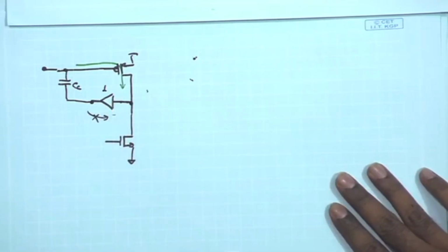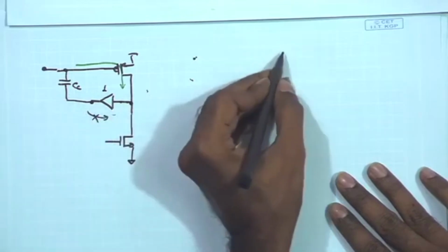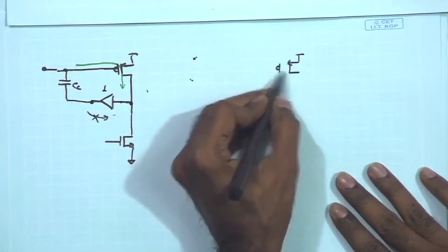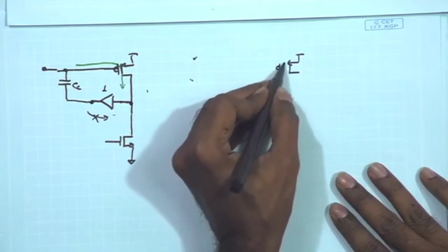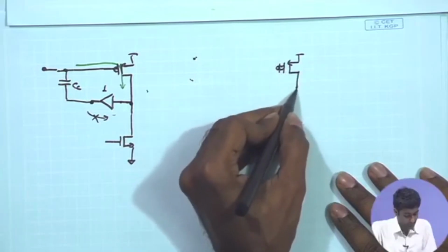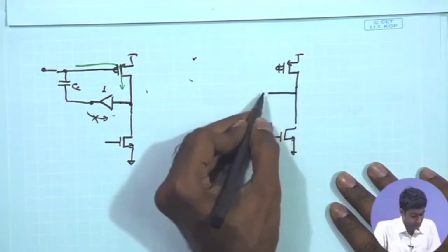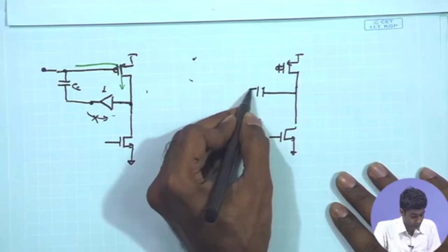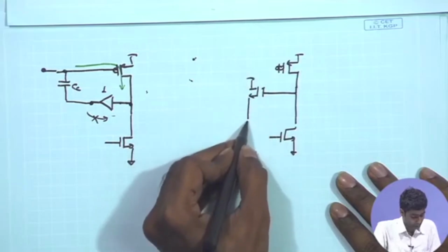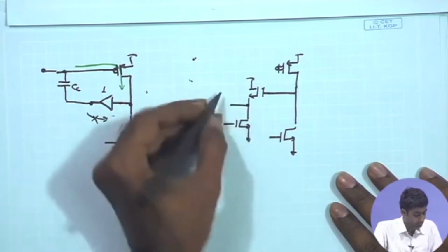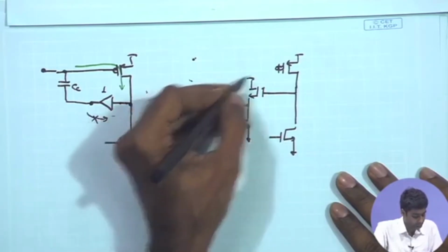Now, in order to implement this particular amplifier, as I said, the simplest strategy involved is to use a common drain amplifier. So, we can think of inserting a common drain amplifier. So, in that case our circuit will look like this: you can have another bias point over here, and this particular point goes to CC.